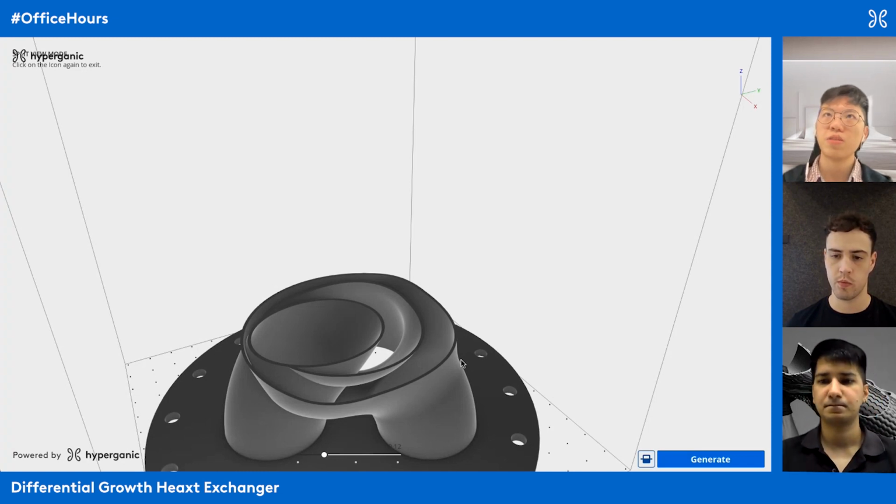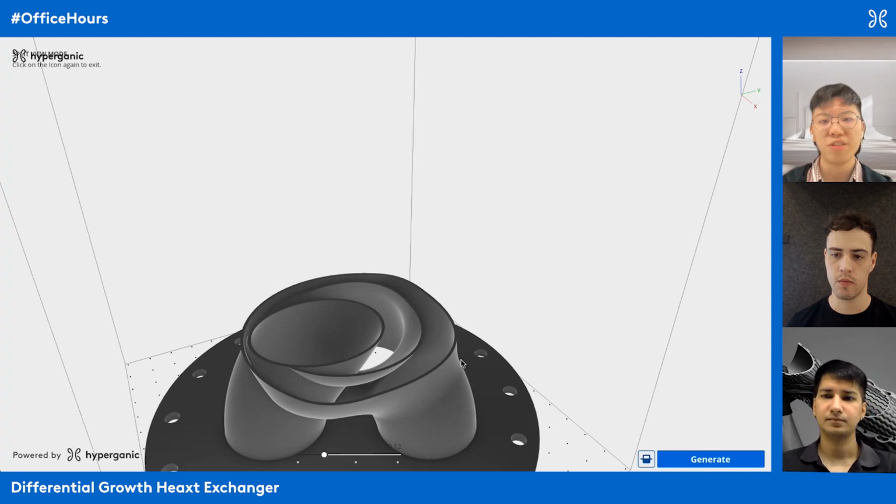Right. I think the next feasible step rather than this would actually be to go into CFD. The reason I say this is because developing more sophisticated equations that are more realistic is going to be more effort compared to using CFD results to govern perhaps pressure drop or whatever we are trying to optimize. Because once we have these different CFD results, we are able to know at certain regions, maybe we have a really high pressure drop. So at this region, maybe we want to modulate the cross-sectional area to account for this in some manner. And this is going to be a more sophisticated approach compared to trying to optimize upon our first initial guess, because all those would still need to be equation based, which may not necessarily translate to being equivalent to real life behavior. So I would say that the next natural approach would be to use CFD.